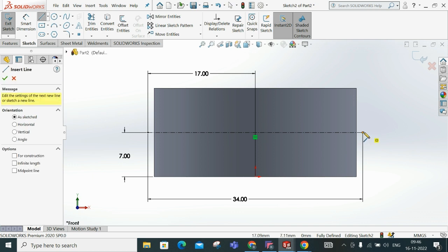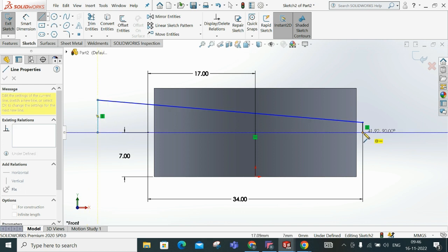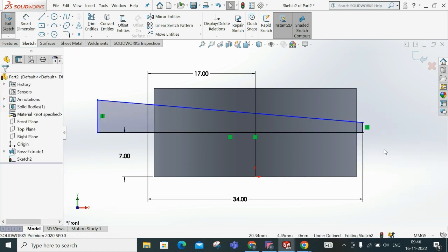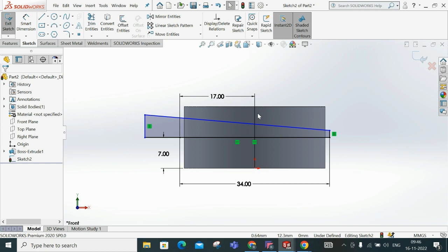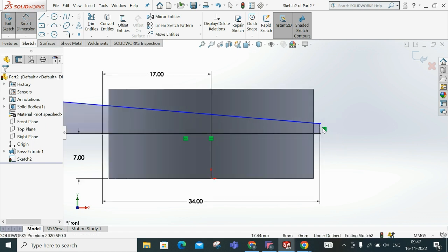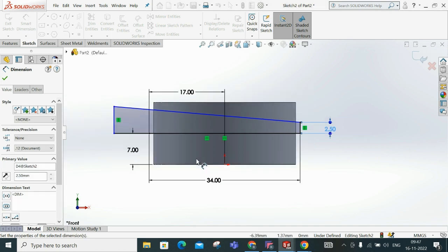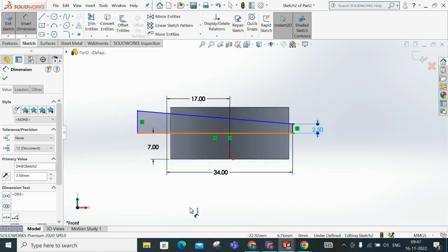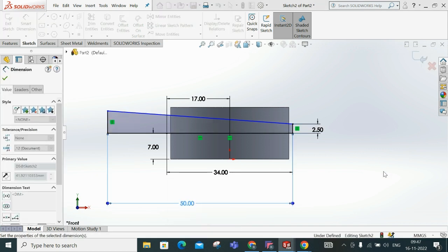You see, the way to draw it is: here it is 2.5, and when it goes to a distance of 15, that should be 3. Here the distance is 2.5, that is half of 5, and 1 is to 50 means when the length of the taper is 50, there should be 1 mm increase in dia.